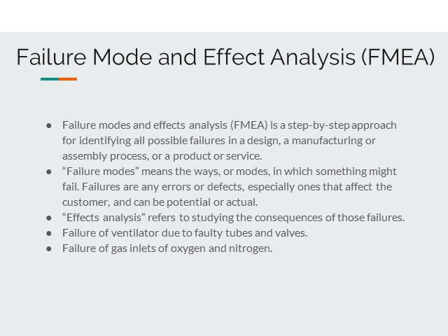Failure modes and effects analysis is a procedure for identifying all possible failures for different stages of device development. Failure modes are potential sources of failure, and effects analysis covers the consequences of the failure. In this device, a potential failure might be of the ventilator due to faulty tubes and valves, or failure of the gas inlets of oxygen and nitrogen.